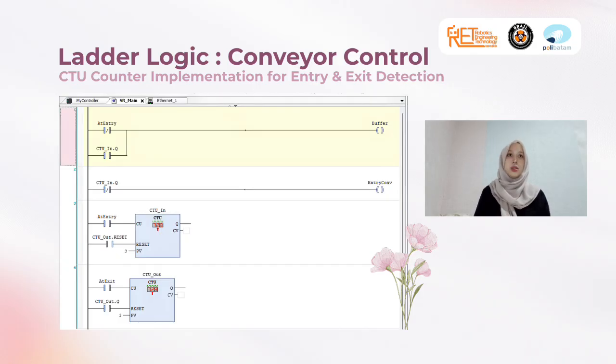To reference a specific input or output that belongs to one instance, IEC 61131-3 uses dot notation, where it is instance name, dot, then the output or input name.